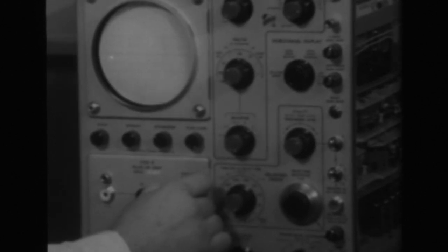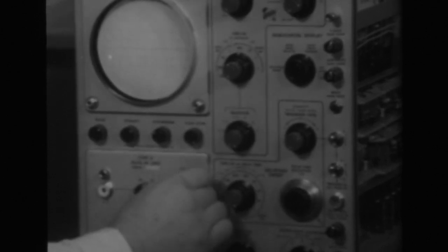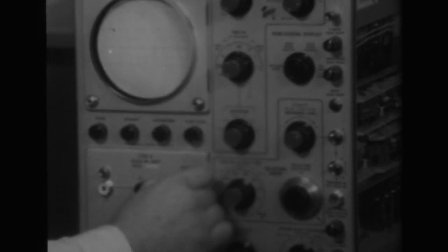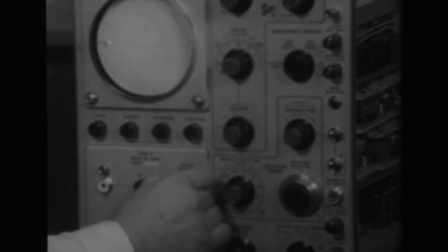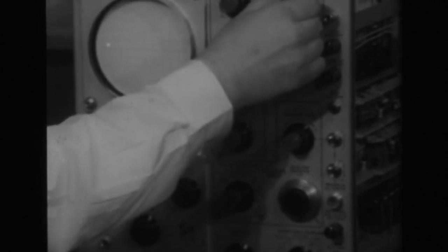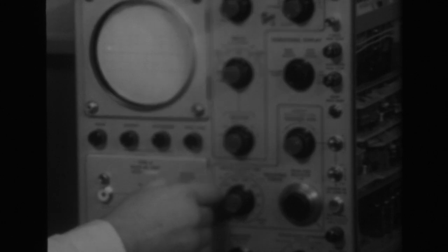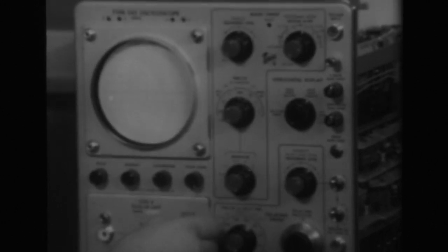And as that spot approaches the horizontal center line, note that the trigger circuit causes the sweep generator to produce a trace right at the horizontal center line. If the position where the trace is generated occurs on the center line for both plus and minus positions of internal trigger slope, you have made a correct series of adjustments so far.